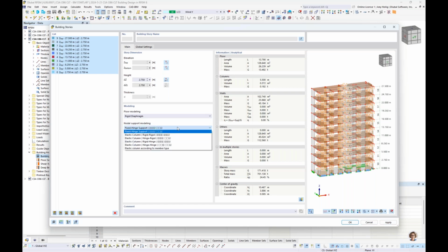The nice thing and powerful thing about the building model is that we certainly can set this to a fully rigid connection for our nodal supports or our line supports, which is more or less what we saw in example 1. But the building model can also calculate the true stiffness of these concrete shear walls or CLT shear walls that are framing up underneath it, or the columns, to apply this as an elastic stiffness instead for both the line supports and the nodal support. So these are the various options that are available to us. Now for our rigid diaphragm today, we're just going to leave this more or less as fully fixed conditions that we see here for the relevant degrees of freedom.